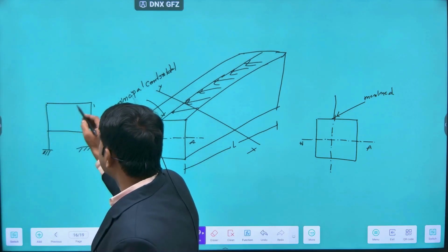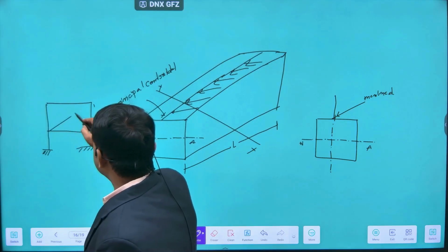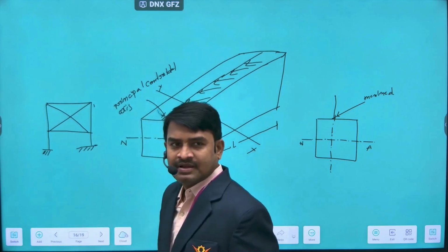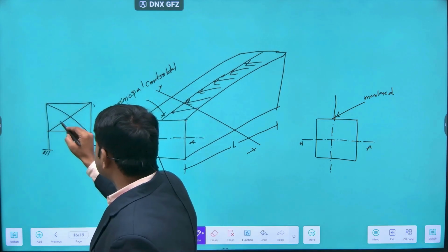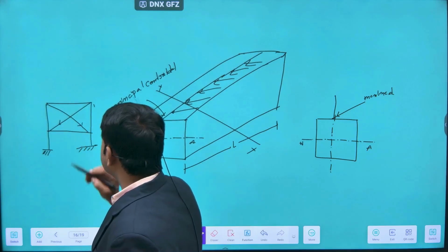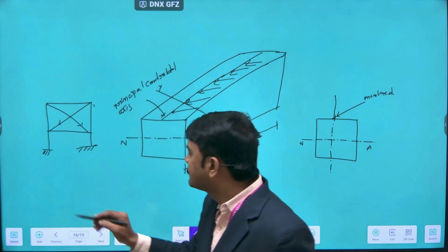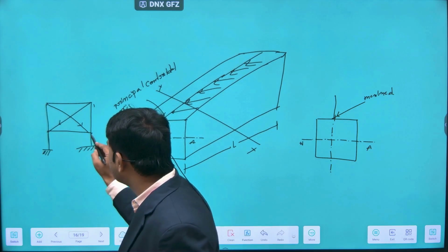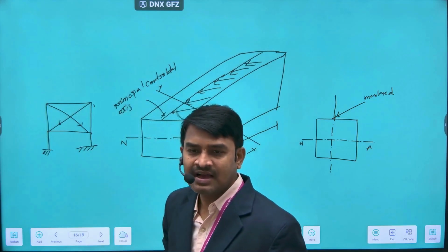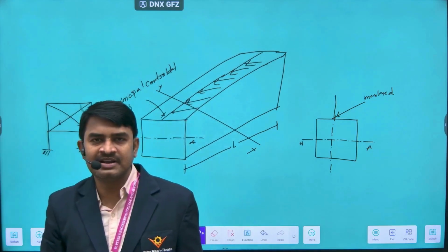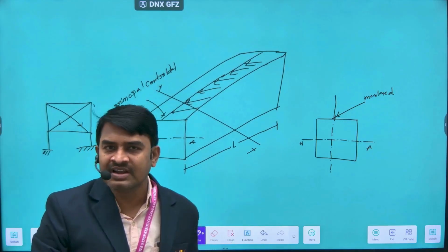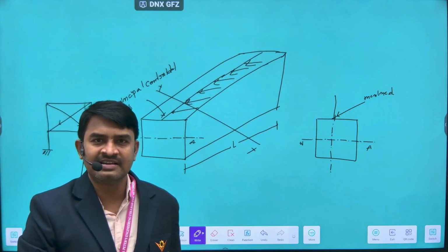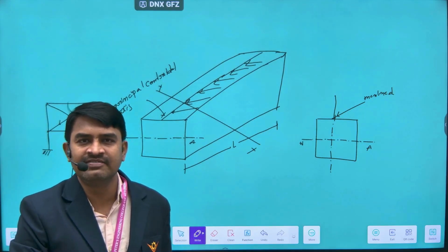This is the frame. In this case, the inclined beams on the framed structure have inclined load conditions. At this point of contact, it transfers the load into vertical. So this is the unsymmetrical case. Unsymmetrical bending is very important in civil engineering, because without it, the design of steel structures is very difficult.